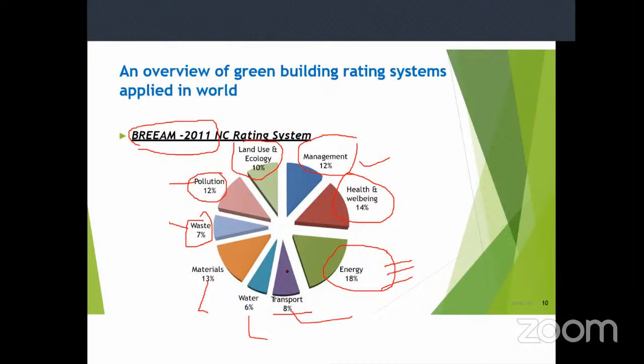There they have a level difference, RL difference. Do you know how it was? We looked at the minimum and highest on the contour map. The elevation difference between the minimum and highest was about 12 meters. They have not filled this 12 meters with soil. That's not possible, that's not economical. From where will you get the murum and all? They have done leveled parking. They made 3 to 4 level parking and then put the IT mall on top.